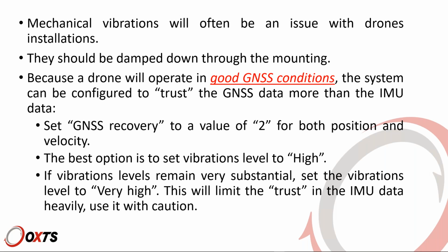Because we assume that a drone will be operating in good GNSS conditions, because drones will fly over things, so hopefully you will not have a lot of obstructions in the way, we can configure the system basically to trust the GNSS data more than the IMU data. Because the GNSS data is good, open sky, and because the IMU might be suffering from some vibrations, this is what we do. We put more weight on the GNSS.